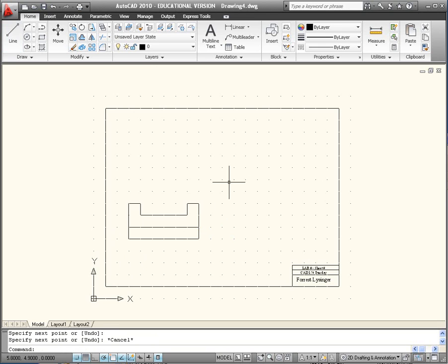We're going to come up here and we're going to put a 45-degree line in, and that's going to relate our top view to our right view. So the next thing I'm going to do is draw the top view. And that's 3 wide and 2.5 tall. And I'll put in all the features that I can do immediately on there.